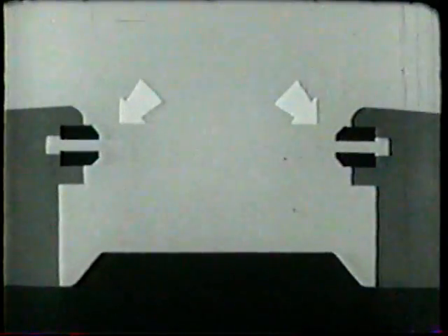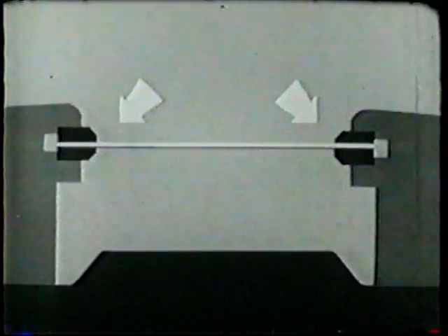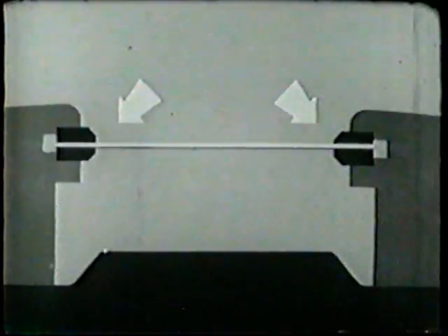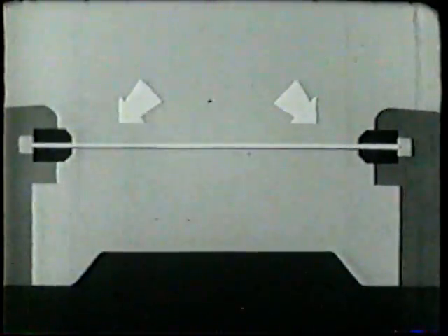The stretching process is based on the action of vise-like grips in which the edges of the aluminum alloy section are inserted. As the tensile load is applied through the grips, the metal is stretched, the equiaxed grains becoming elongated and oriented in the direction of the applied load. These grain changes increase the strength and hardness of the metal.